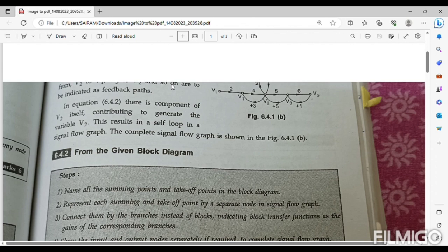Further, there are some sets of rules and regulations. You know that in a signal flow graph we have nodes, a forward path and feedback path, and many more. You know what all the terminologies present in a signal flow graph are: source node, sink node, chain node, forward path and feedback loop, as well as self-loop path gain, dummy node, non-touching loops, and loop gain. All these are the components of a signal flow graph, and you're supposed to meet all the components in the signal flow graph when you reduce the block diagram to a signal flow graph.